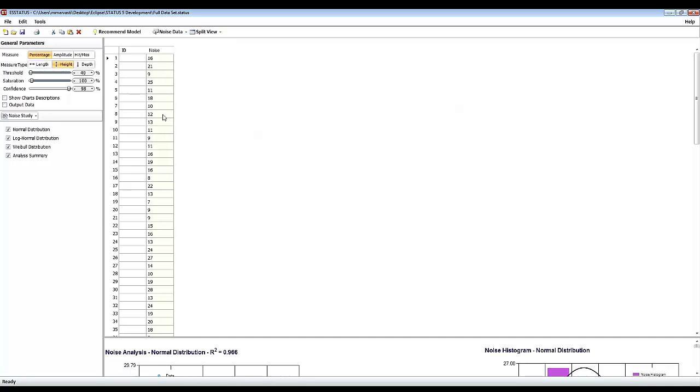Again, the way that you can be sure is because you are doing all these on well-defined, pre-known samples. So you know those samples and you know the locations of defects, so you can bring your probe or your acquisition unit to a location that you're sure has no defect and record the amplitude. If you do that, that amplitude can represent the background noise amplitude. And you need to have at least 15 random locations and 15 random numbers that give you that noise.